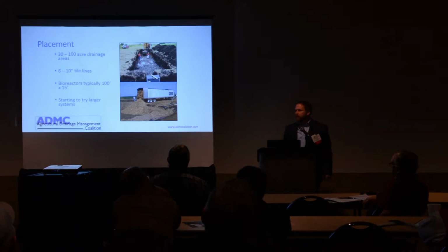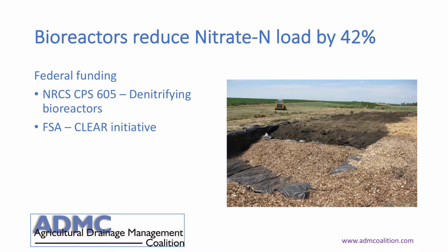I guess that's fine. It's a tight soil, like a clay soil. Once you get down there, it's really not needed because you're just going to lose such a low amount of water. But over the top of the wood chips themselves, in the next slide, there's a geofabric. So here's plastic on the side. This is a geofabric, geotextile fabric. And so that allows water to move through it, but it keeps soil particles from moving into the wood chips.